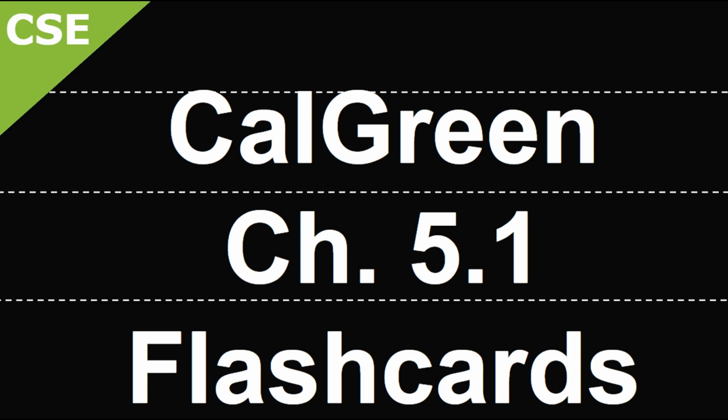The electrical system and transformers must also have capacity to supply full rated amperage at each EV capable space. And finally, the sub-panel circuitry label must show EV capable.